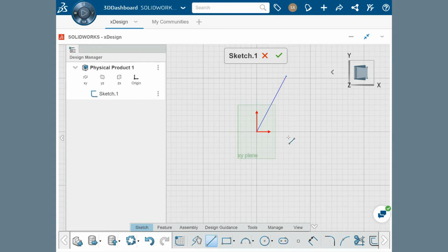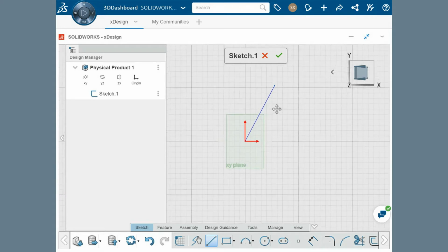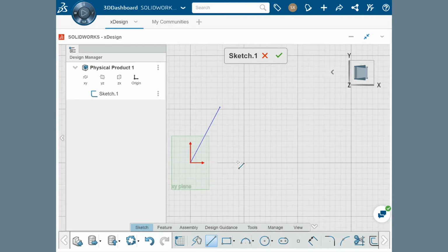As you can see, this line can be created at any angle and has no other geometry being created once I double-clicked. Another way of making this same individual line is by clicking and holding the mouse button at the first endpoint, then moving over to the location of the other endpoint with the mouse button still held down, and releasing the mouse to create the other endpoint.